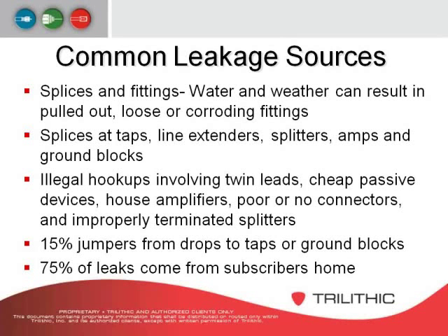Some common leakage sources are splices and fittings, similar to what we talked about. Water and weather can result in cables pulling out of connectors or loose connectors. We'll call those suck outs. Corroded fittings or splices at the taps, line extenders, splitters, illegal hookups, and twin lead cable.